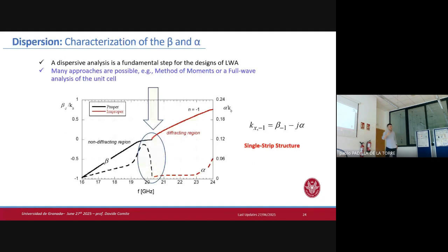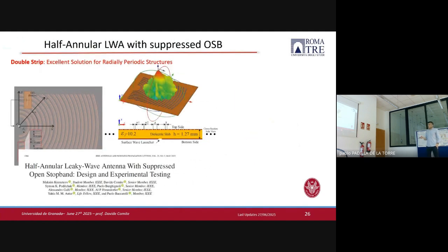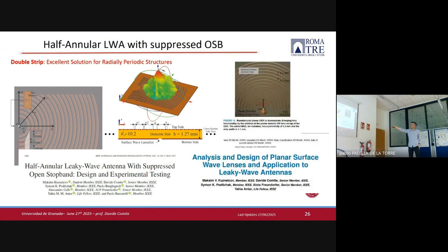So you are making an antenna that is planar, with a feeder that is fully integrated, that is ready for the broadside. Doing the same with array theory means that you have to use multiple feeders. It's a bit different, probably a little bit more complicated. Or then you can do different shapes, sectored, and then you can get beams that are highly directional. Still, we have the same dispersion, the same behavior, but you can get fancy beams, for example fancy beam scanning. So you can do different things with a planar antenna.